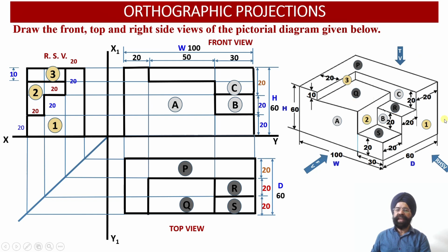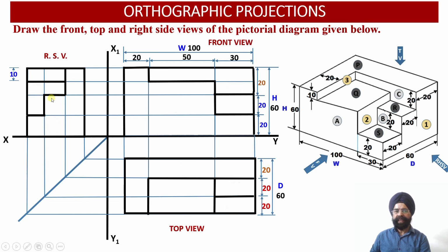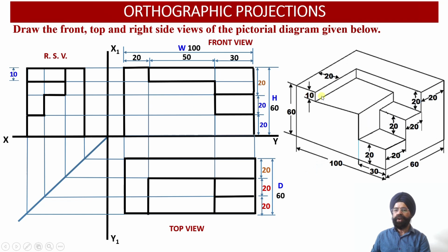With this we have been able to obtain the orthographic projections of the solid, but we have surplus dimensions which we can afford to omit, and we can omit the special markings which we had made corresponding to the surfaces, so that we can have visualization and understanding of the orthographic views obtained, right? So we have removed the markings from the projections. From the isometric projection also I have removed all these markings, and finally I am going to remove these dimensions.